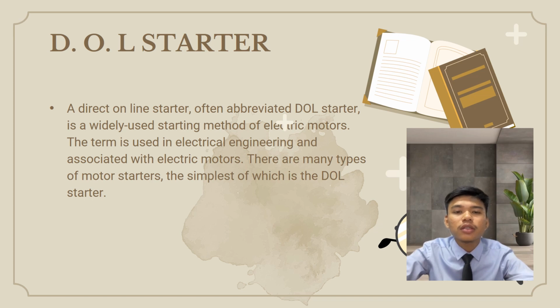Although DOL motor starters are available for motors less than 150 kilowatt on 400 volt and for motors less than 1 MW on 6.6 kV. Supply reliability and reserve power generation dictate the use of reduced voltage or not.